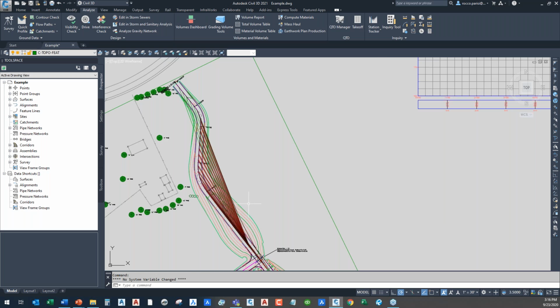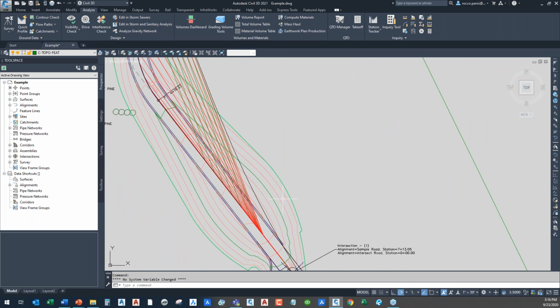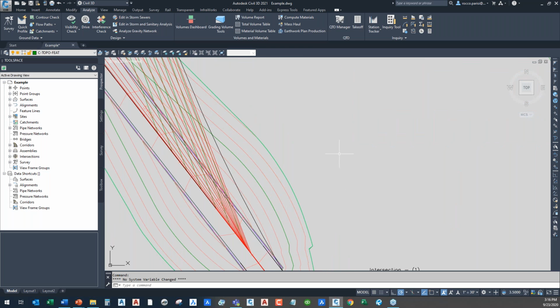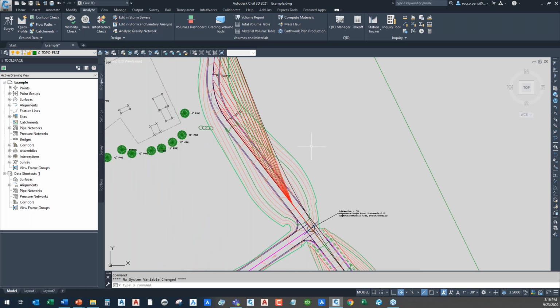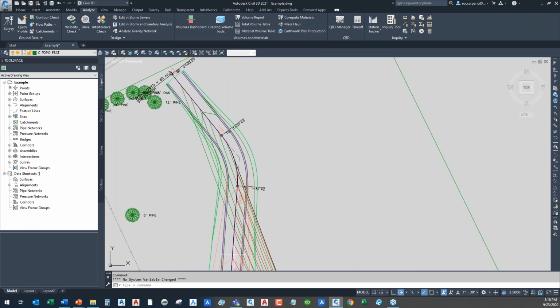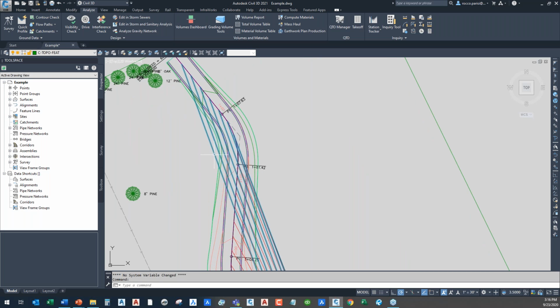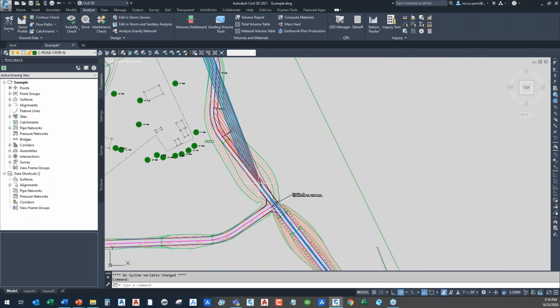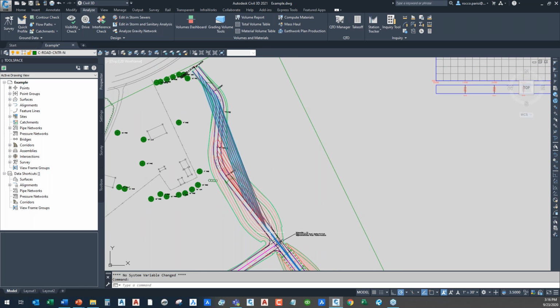And you see it checks the rows. And now you can actually see it's showing me, in red, the obstructed areas, and I can actually tell where I have issues. And what's nice about these is you can see that up here, I'm fine. My sight lines here are the green lines. It shows you what you can see from up here. You see that I can see from this point all the way out to here, but that I actually have some obstructed sight lines coming the other way.